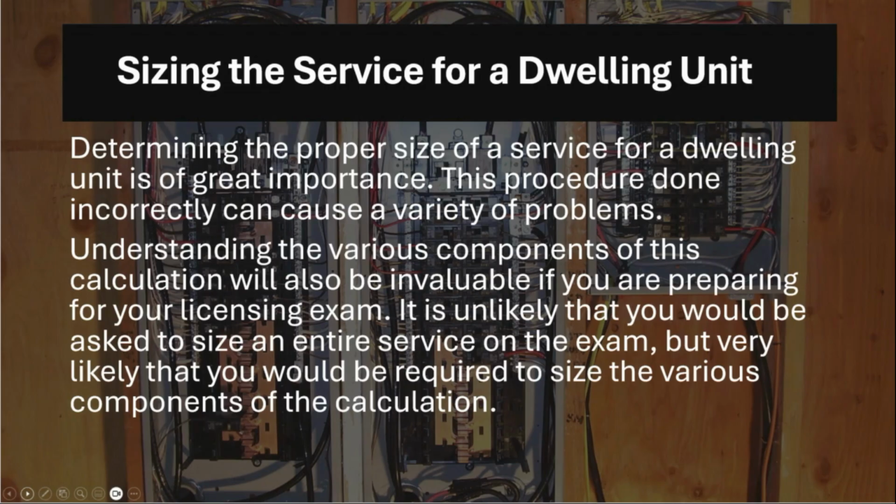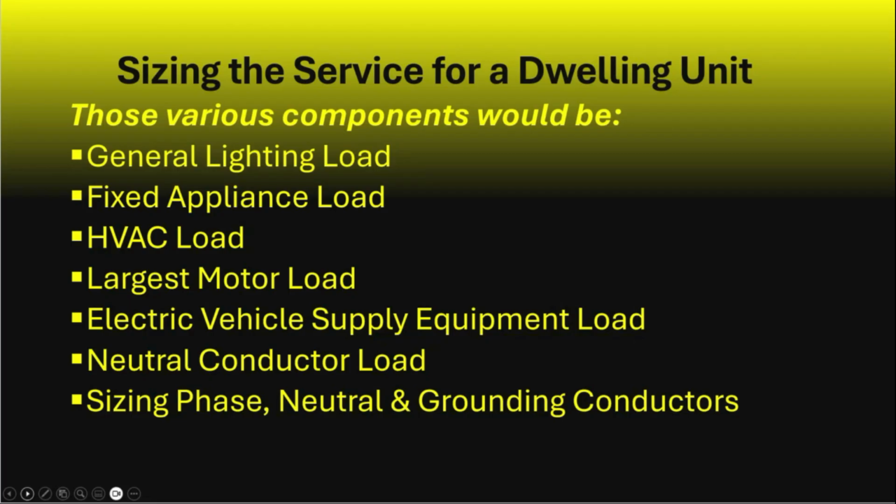It is unlikely that you would be asked to size an entire service on the exam, but very likely that you would be required to size the various components of the calculation. And I should add this caveat, that's really speaking toward the journey level exam. I think you could maybe on the master's exam have a requirement to calculate an entire dwelling unit. And those various components would be general lighting load, fixed appliance load, HVAC load, the largest motor load, electric vehicle supply equipment load, neutral conductor load, and sizing the phase, neutral, and grounding conductors.